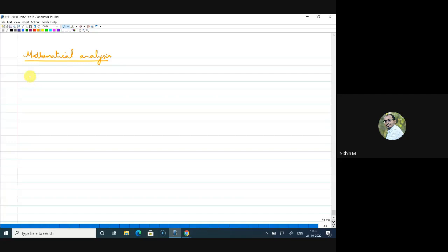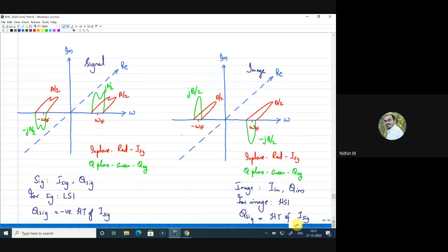Yeah. So I'll write the input signal x of t. While writing the input signal, there will be an amplitude. I'll write it as A signal, and it is cos omega c t with a small phase shift, which I call phi signal, plus the image amplitude A image with cos omega image t plus the phase shift on the image part. Right, this is the original input signal we have taken first.